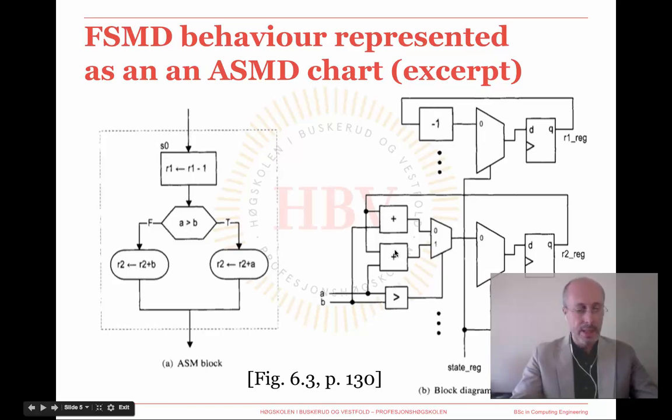By looking at this diagram, you will notice that all combinational operations are performed in parallel, that is to say, at the same time, but the destination registers will be updated with the corresponding results only when we are in state S0, according to the state register control signals at the bottom.